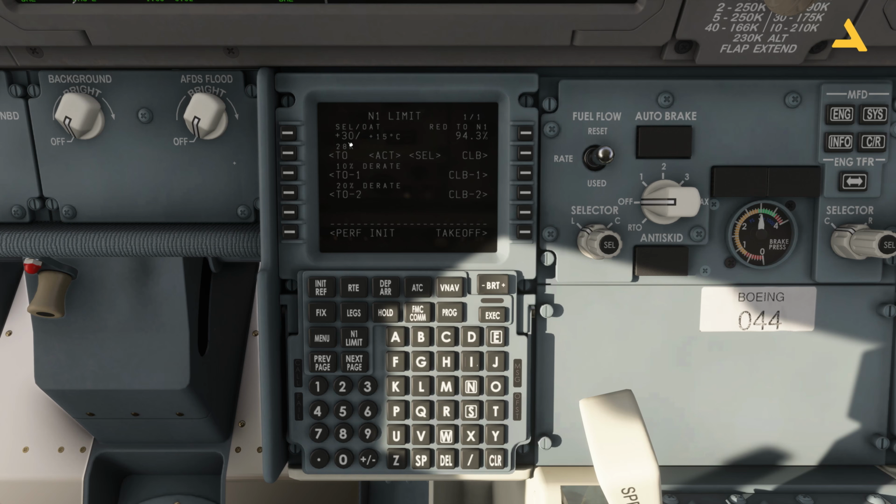Actually, this is also useful when you have a proper takeoff performance calculator. You can use the one available in SimBrief to do this. But as I've told you before, for this video, I will not go to SimBrief because mostly the people are not really comfortable with that tool. Now let's get the takeoff performance calculation, and flaps will be 5.